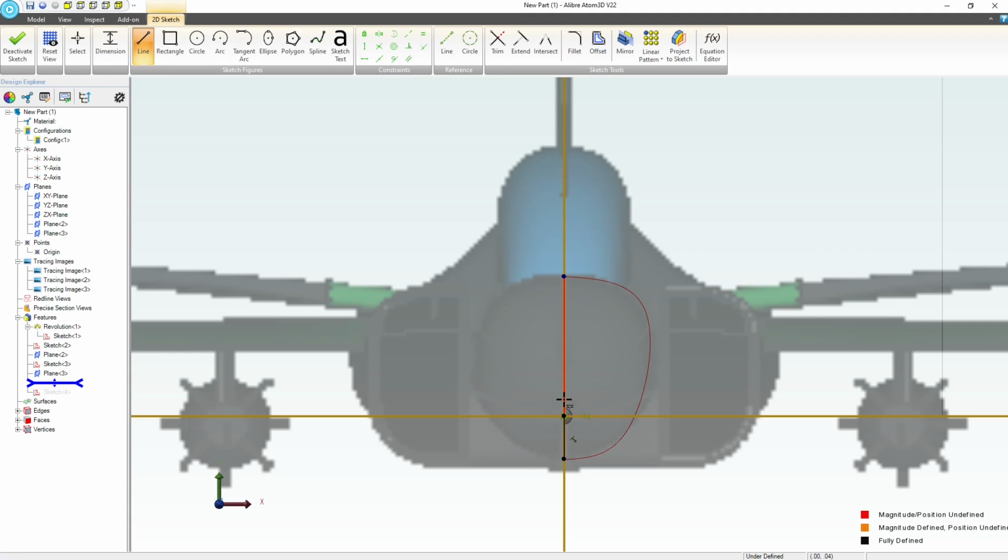And I am going to have that come down. Great. So it looks like that's probably the lowest that our plane will come down. Now I just want to create a multi-point spline that is going to start to recognize our difference in geometry, right? We start to come out there a little bit. And we want our spline to be about horizontal. About horizontal down there. It seems like it does that pretty well.